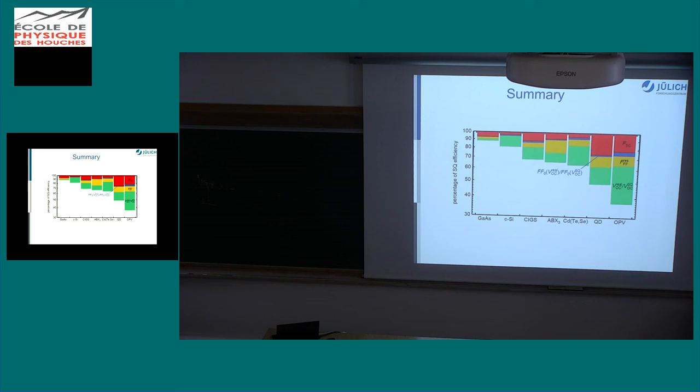Then the same thing is what you have in your real open circuit voltage related to your Shockley-Queisser open circuit voltage. The only thing which is a bit critical to find is really to have the right proper band gap energy. That's the same definition for all these different materials, but then you can do it relatively easily.